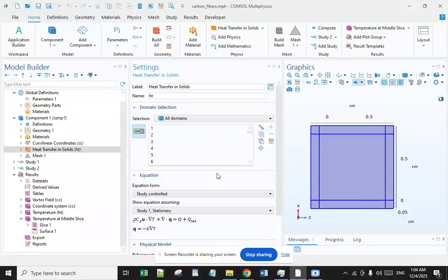The effectiveness of the analytical method is validated through finite element method analysis and experiments. The interphase thermal conduction models are established based on the geometrical morphologies of the nanofillers and the interphase bonding states in WFP composites, which explain the heat transfer mechanism of WFP composites modified with different nanofillers.